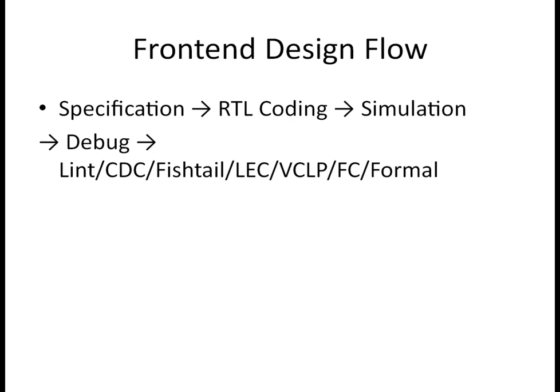your data will go to metastability, right? So in that case, what this two flop synchronizer will do: the first flop, when data is coming, will go to metastability and will make sure that data is recovered in the first flop, and the first flop's stable output, the second flop will sample. So in that way we are synchronizing the data going from one domain to another.